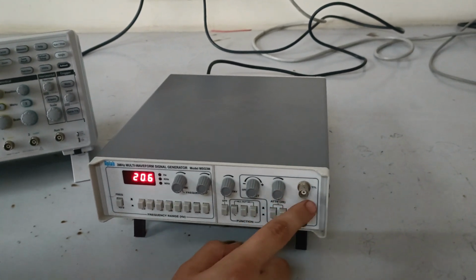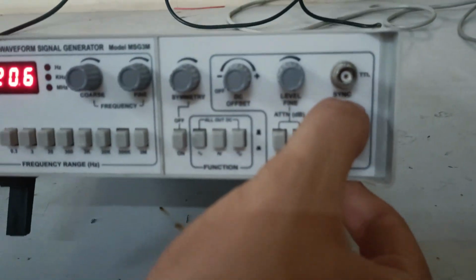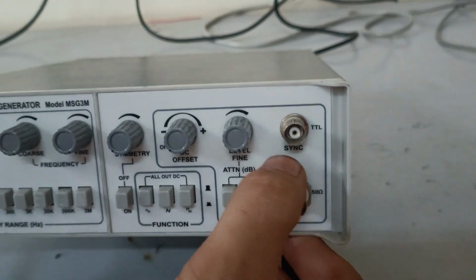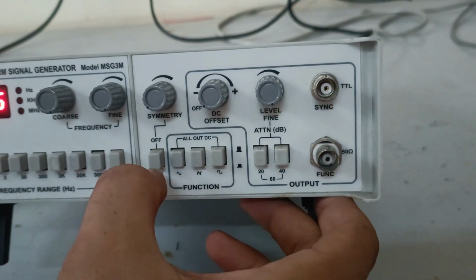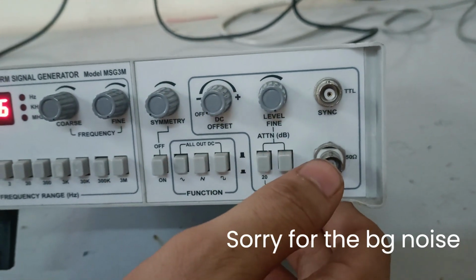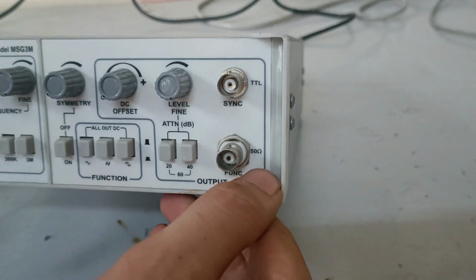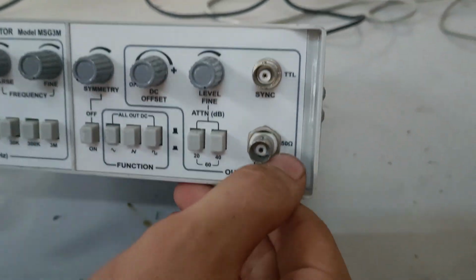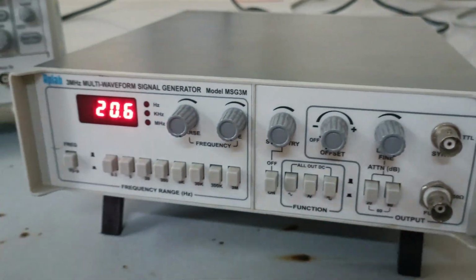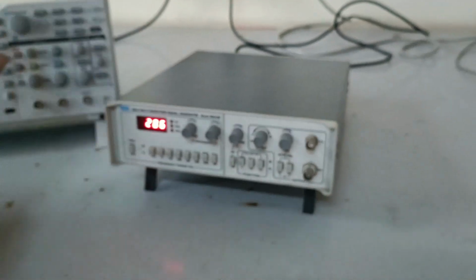The first probe is labeled as TTL and it has "sync" written on it. This probe basically provides the digital signal, that is a square wave. So no matter what type of wave we apply, it always gives a square wave as the output. It gives a digital wave. The second is the function output. It has 50 ohms written right here because the impedance of the function generator is 50 ohms. That means the probes we are going to use are 50 ohm probes so that they give the perfect output.